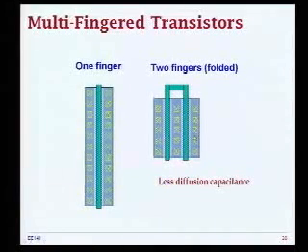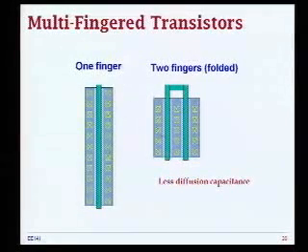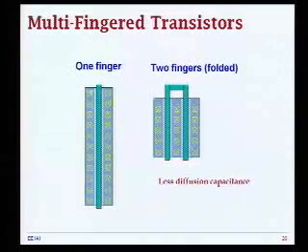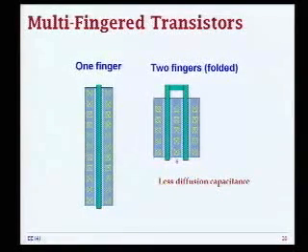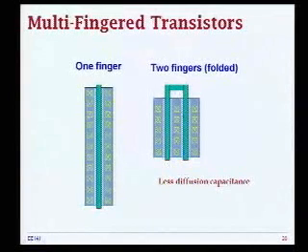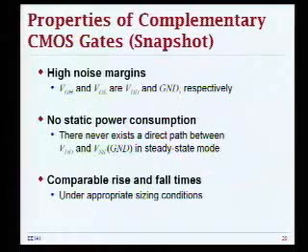And this is really, if you have access to some of the standard cell libraries, just go open, for example, a 1x buffer and open an 8x buffer. And you will see exactly this situation. You have a fingered implementation of the same transistor width. So what happens here is basically that you eliminate a lot of these contacts, and you have consequently less diffusion capacitance. So you have better performance out of your device.